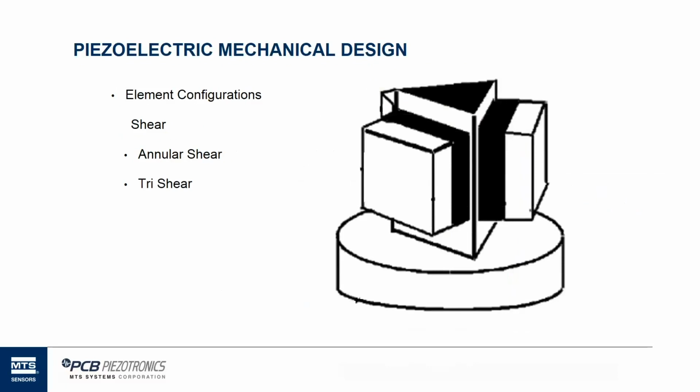It makes that mechanical post much stiffer and drives out the mechanical resonance of the sensor to a very much higher frequency. And it also gives us basically 3 times the output of the crystal configuration. So we like that because it gives us higher sensitivity, higher resolution measurements, and higher frequency too. So those are the basic mechanical designs we have.